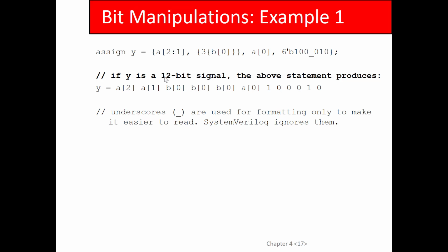What is that going to be? Well, A is 0110. So that's bit 0, that's bit 1, that's bit 2, and that's bit 3. So bits 2 down to 1 is going to be those middle 2 bits out of the 4, which is 1, 1. Make sense? Can you read that from there? So that would be equivalent to 2'b11. So it takes out the 2 middle ones.